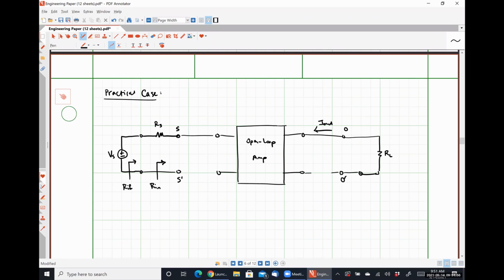Okay, so I want to talk about these real quick before I connect my feedback system. If we were trying to measure our output resistance with feedback, ROF, this is a set of terminals effectively that tells me where to break my feedback loop to measure my output resistance. So it's always going to be between my load resistance and then my feedback network. This is how I'm going to break it to be able to look in and see what my output resistance with feedback is.